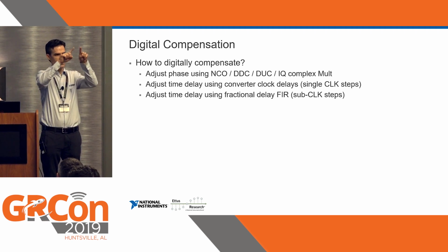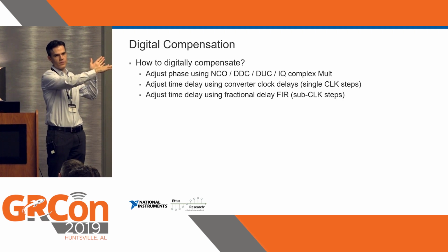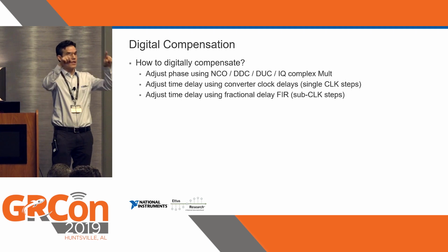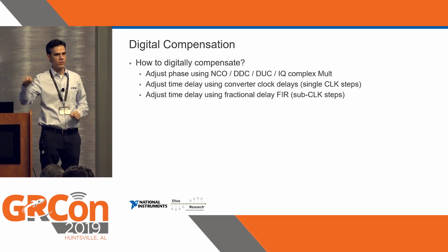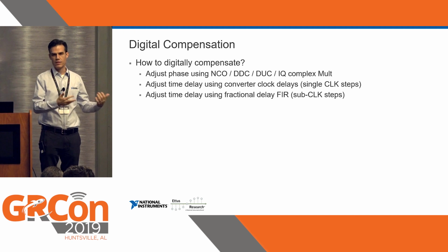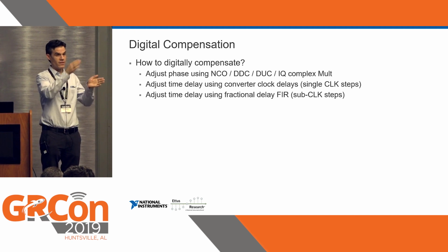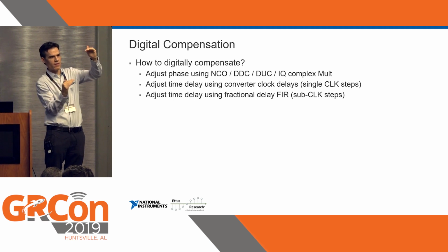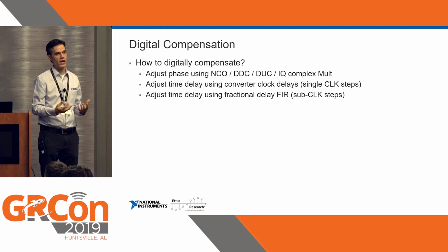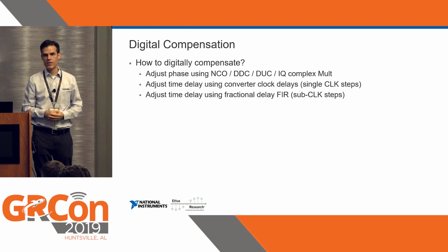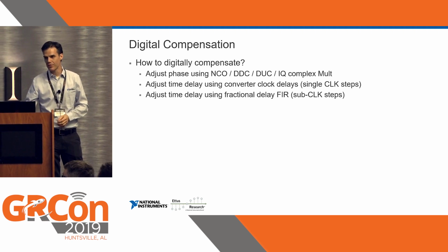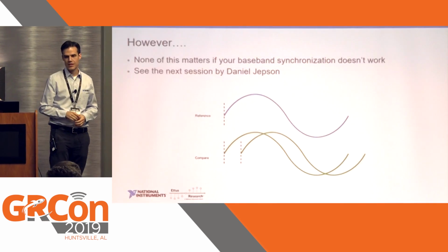So when you take that continuous time, an all-pass filter in the frequency domain is going to be a sinc response in the time domain. And if you have a continuous time sinc response and you want to sample that to create a discrete time sinc response to make FIR taps out of it, you don't have to center where you sample those points. You could move those points ever so slightly to the right or to the left, and you can get a fractional group delay out of it. And if that made sense to you, that means you probably already know how to do it. If it didn't, I'm sorry. I decided there wasn't going to be enough time to fully cover it in there. But if you want to talk about that, come find me afterwards.